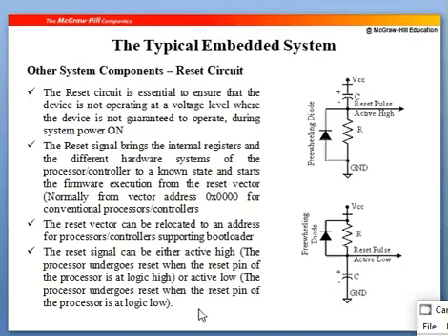When you pick that word from address 04, the jump goes directly to the reset handler subroutine, and the content present in that subroutine will be run, which is used for rebooting your controller or processor.